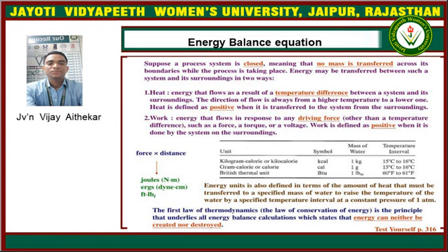The second form is work: the energy that flows in response to any driving force other than a temperature difference, such as force, torque, or voltage. Work is defined as positive when it is done by the system on the surroundings. Force times distance is measured in joules, or newton-meters.